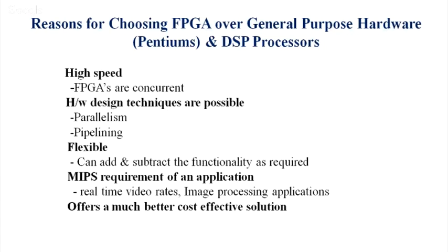If you want to use an ADC and it has 12 channels, then at one time it will only take one channel. After that, it will take the second channel. After that, it will take the third channel. But in an FPGA, if you connect the ADC, it can take all the inputs at the same time, because it has different controllers. This is the main thing we talk about, parallelism and sequential. Okay. Next, we have also shown you that parallelism and pipelining are the most powerful tools of this FPGA.